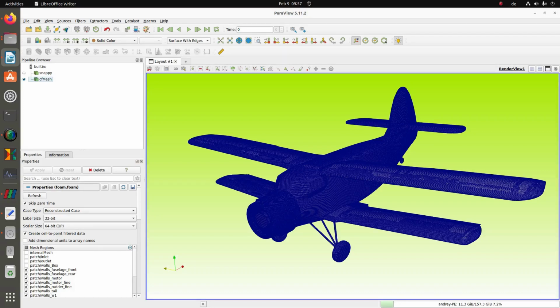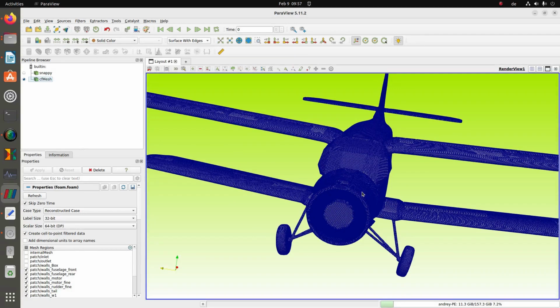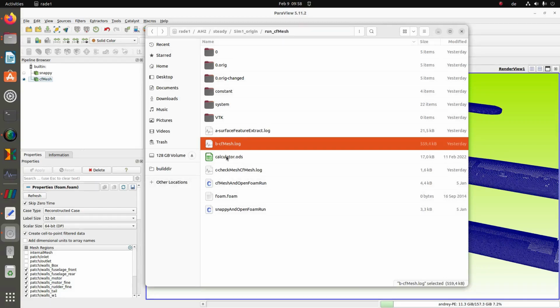Maybe it will be a possibility if I change the global cell size and make sure that the cell size on the ribs will be between 1 and 2 millimeters. Now I know that 1 millimeter cell size causes too high a number of cells in total, and refinement of 2 millimeters cell size creates a too coarse mesh. For that I have two options. Let me show you a calculation.